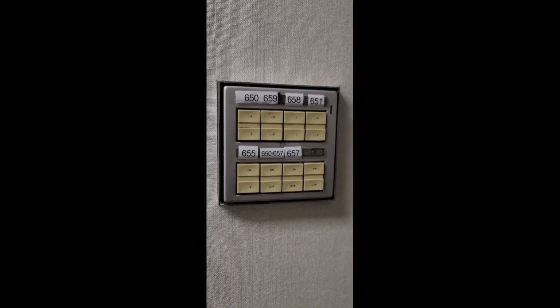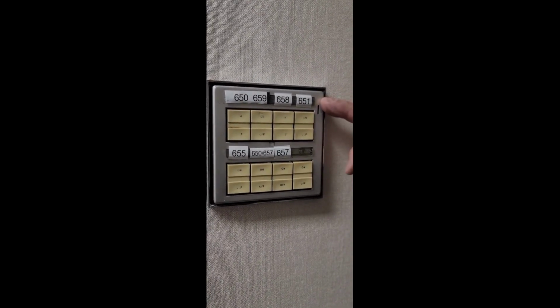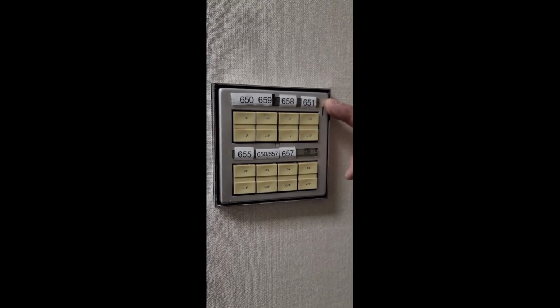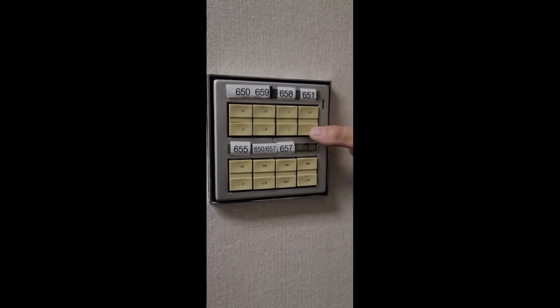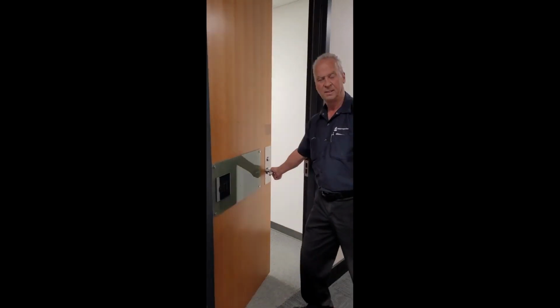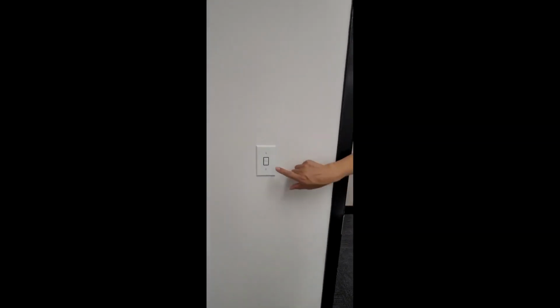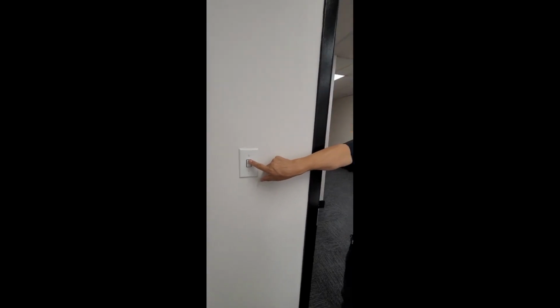Okay, so we had a complaint that vacant suites such as 651 are not turning off from the hall switching. If I press the off switch, and you'll see 651 right there, the lights do not go off. So the second step would be to go into the tenant space and check for a tenant light switch, which is a secondary control. We'll go into the tenant space and we'll find, yes, the tenant does have an internal light switch. Now we'll press the off and the lights don't go off. So now we have an issue with the relay problem where lighting is not going off by the low voltage switching.